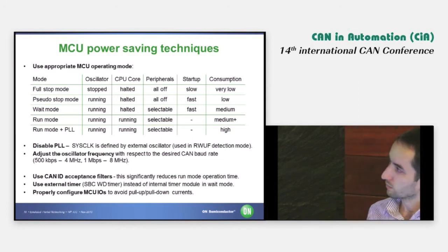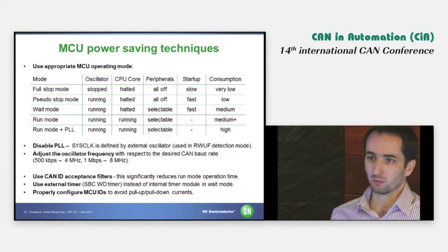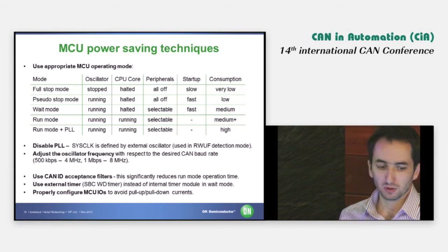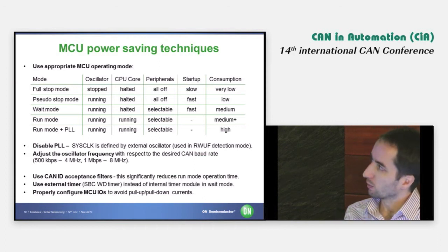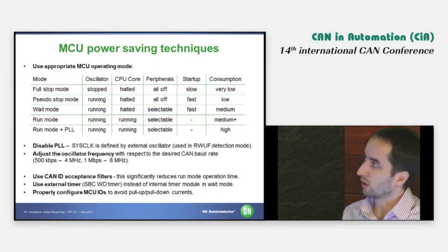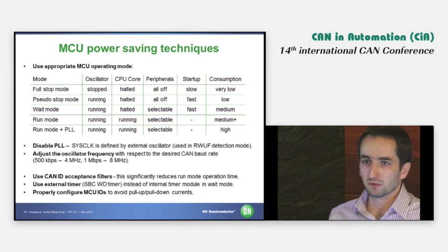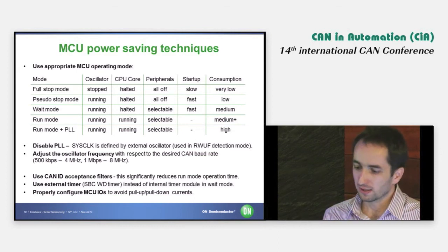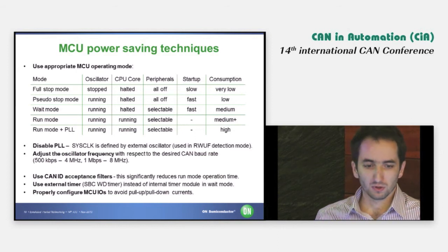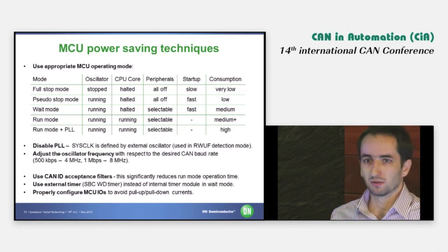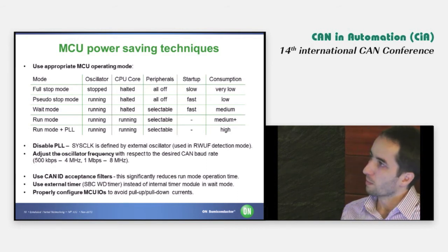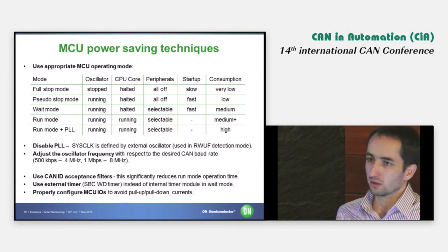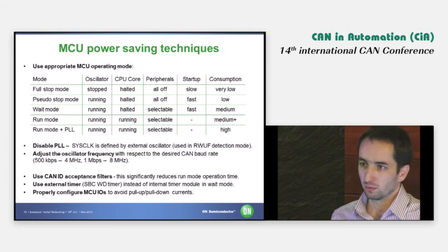Most of the time, if we want to run in a low power mode, we are in the pseudo stop mode, where, as I mentioned, almost everything is disabled, and the physical transceiver is in a low power standby mode. So it interprets any communication on the bus as a wake-up, and it reports this wake-up to the microcontroller.